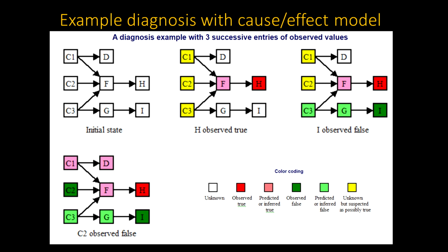And note that they're interconnected. This is different than a typical fault tree analysis you do that came out of the nuclear industry. Those diagrams are kind of problematic in that they're all assumed to be trees, but what happens is you work your way from a cause down to all the things that could lead up to it. And the problem is there's really a lot of overlap between multiple trees, and you can end up doing a lot of extra diagnosis. It's much better to have all of the logic combined into one diagram. And that way, when you have common cause problems, all of that can fairly easily be determined.